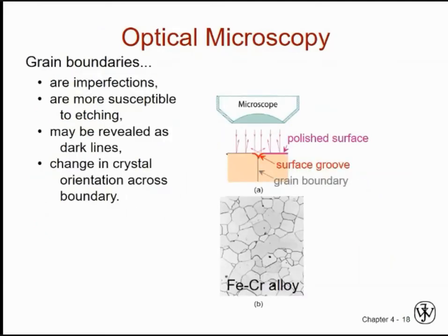Let's continue. So again, we have an element. This one is a grain boundary. Before we apply chemical, that's our grain boundary. After we apply chemical, because the grain boundary is chemically active compared with the grain itself, the grain boundary will be dissolved first, dissolved more compared with the grain. So as a result, the new shape of this element will be something like this. We will create a groove over here; this side is dissolved, not there anymore.